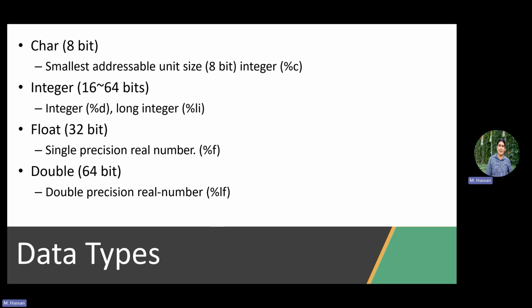It means that all the registers in this chip are 8 bits. Well, there are 16-bit Arduinos and 32-bit Arduinos. What about the ESP32? 32 from the name, right? It's called the ESP32 because it has 32-bit registers. What about our device, the Nucleo board? It's a 64-bit ARM, which is a lot for an embedded system. It's one of the higher performance ones.